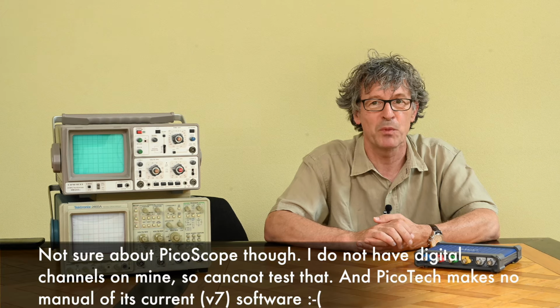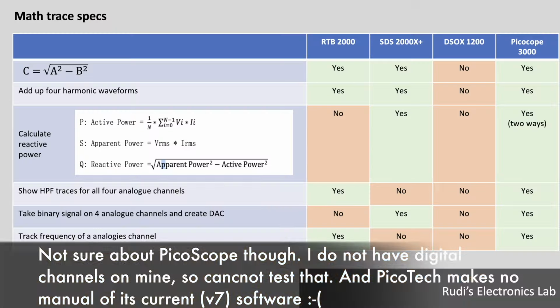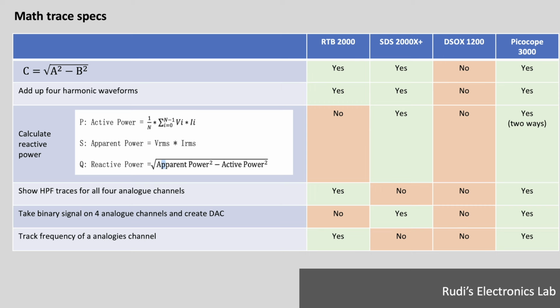Oh, quite interesting, none of them are able to deal with digital channels in their mathematics. I'm a bit disappointed by that, but that goes for all the devices. While again, tracking the frequency of an analog channel, that's something that the Rohde and Schwarz can do and the PicoScope, but the Siglent can't do. So I'm not trying to say one device is better than the other, but they're all very different in terms of what type of things they can do, and we'll dig into the details of that.